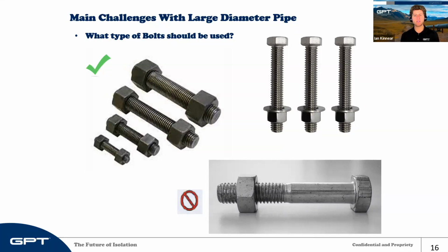The reason for this is because we can ensure that the sleeve is going to fit over this stud, and that the studs provide the ability to obtain more accurate torque values for a gasket than bolts, because studs don't twist during tightening. So if bolts are being used, though, it's incredibly important that these don't have a shoulder on them, like on the bottom.